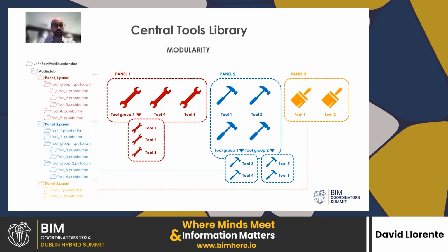PyRevit is modular, and this is very important. As I mentioned before, depending on the structure of the folders, you will get different elements in your add-in. For example, in the red lines, you can read the folders called panel are the different parts of your add-in. We will see an example right now.